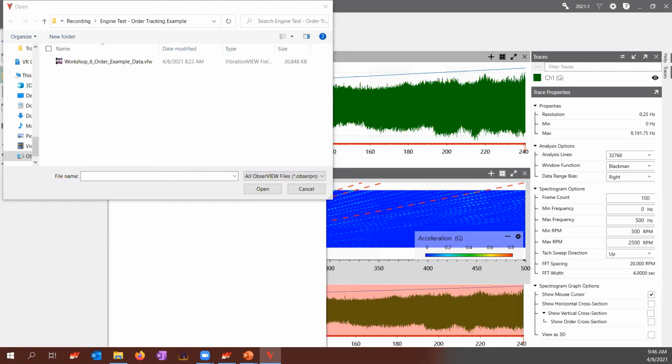I'm not sure about the sign-on random test generation. I know that software has a lot of different things that are targeted more at strain-based fatigue as opposed to vibration-based, but you would have to check with them. But the concepts are open and available. So yes, if you have that data, I'm sure with that software, you can calculate a PSD. So you could calculate the PSD and then just run that PSD in your controller software.